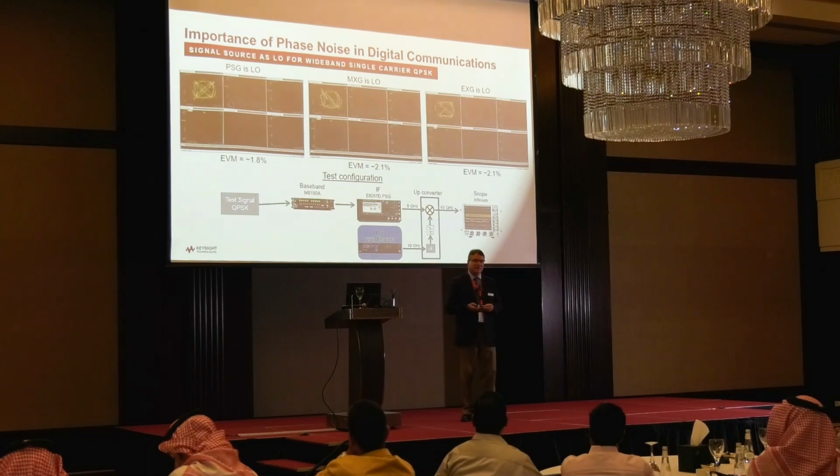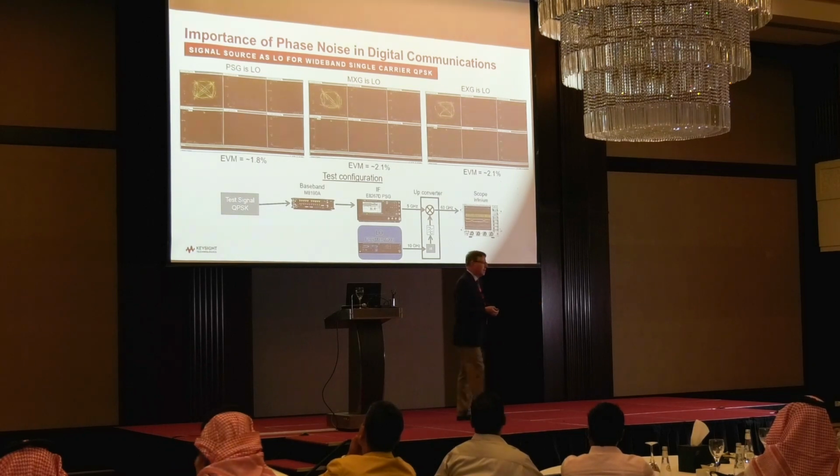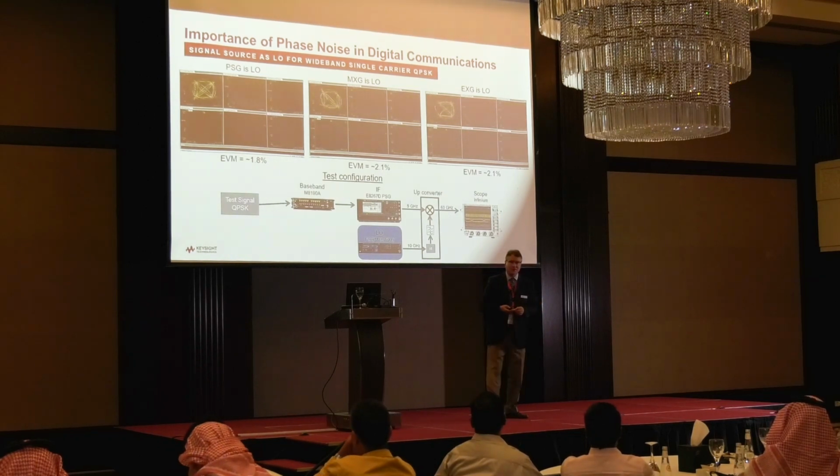And you can see that the quality, which we describe as EVM in the digital comms world, varies depending on which generator I used as the local oscillator for the up converter. And so you can see the EVM is actually the best with the PSG, which turns out is our top of the line microwave signal generator, has excellent phase noise.